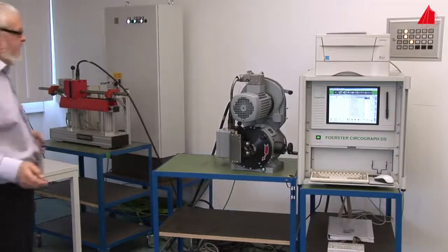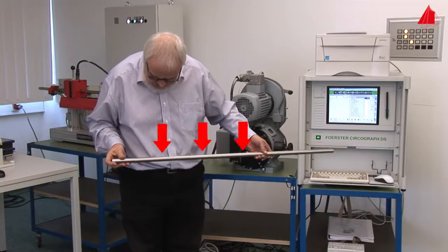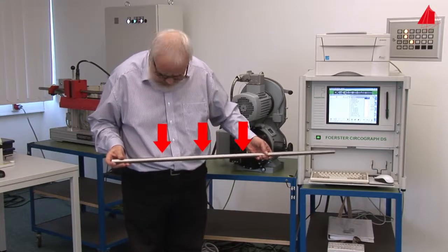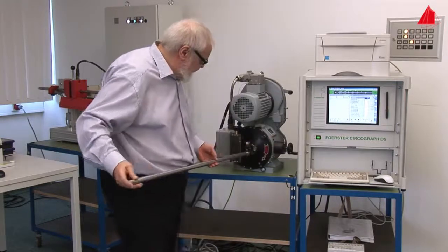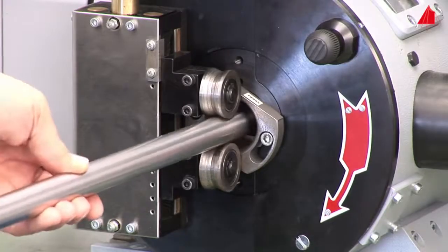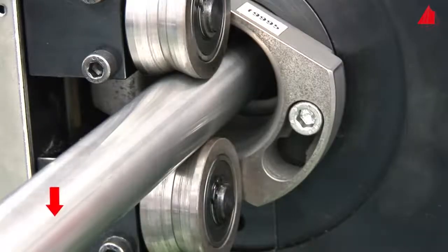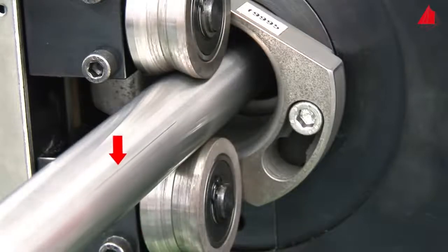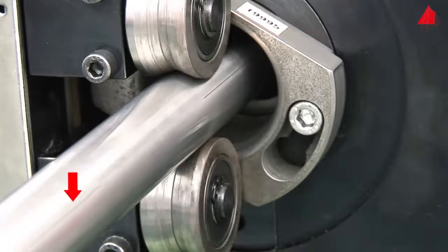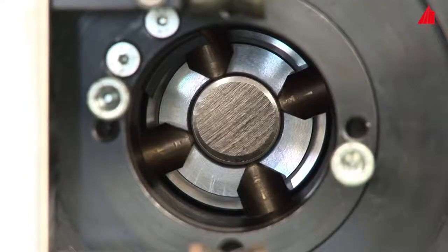This version of eddy current testing is also well suited for mechanization. 3 very fine saw cuts with varying depths have been machined into this massive cylindrical rod in longitudinal direction. The rod is again made of an austenitic steel. The materials tester pushes the test piece with constant speed into the machine, so that the saw cuts pass through the actual test area. A look into the interior of the machine shows the rod in the centre.